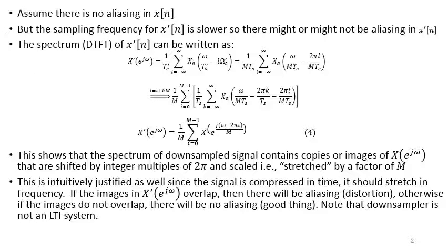In this lecture we'll be talking about downsampling, upsampling and rational rate conversion. So you were on this slide in the previous lecture. You understand what downsampling means. Downsampling means to throw away samples. So if we downsample a signal by a factor of, say, M, then we are throwing away M samples, consecutive samples, from the discrete time signal.